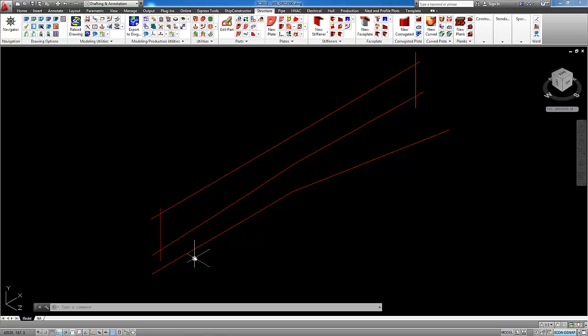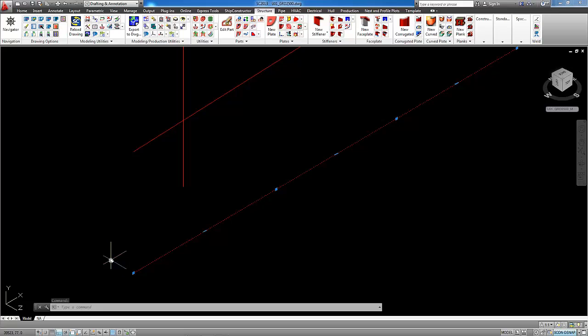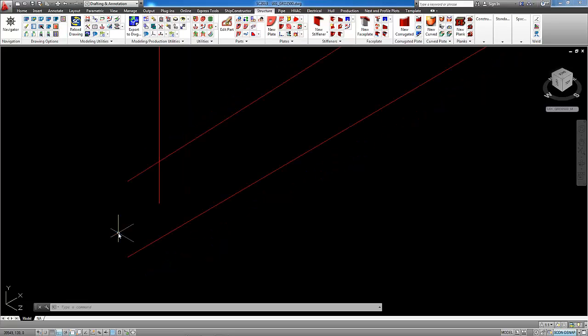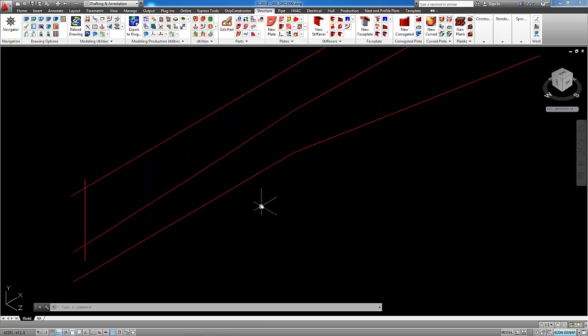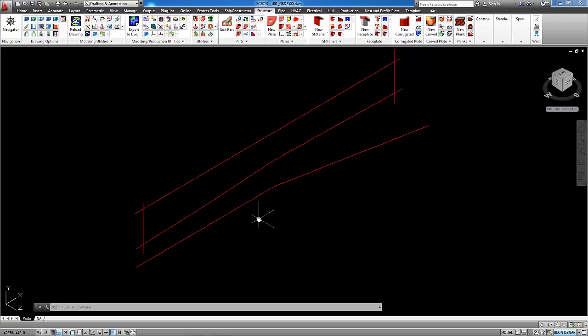But here we have to remember that corrugated plate will be created so that thickness will be centered above the corrugation profile line. So half of thickness will go outboard and half inboard. In this case, if I will use this line, half of thickness will create collision interference between the girder and the shell. I know that my plate part will be 12 mm or 10 mm thick.